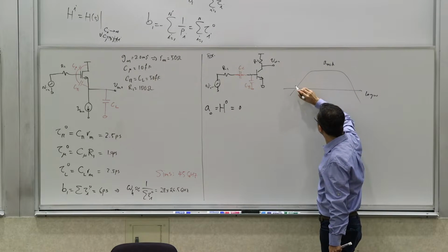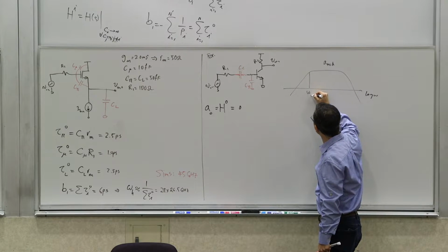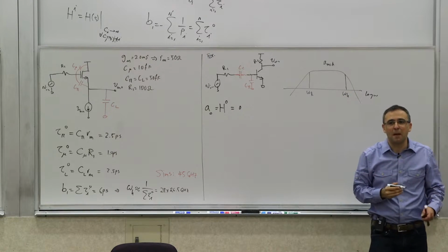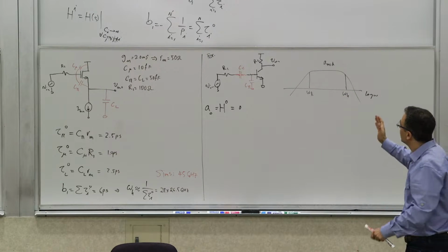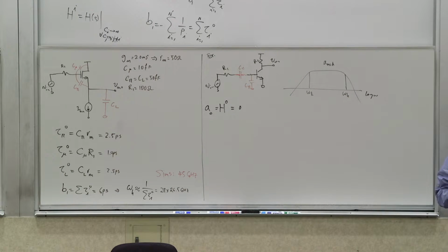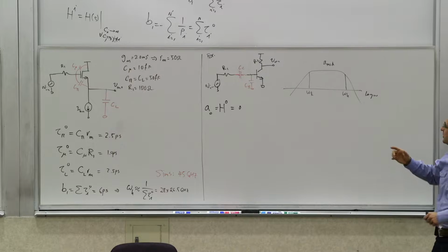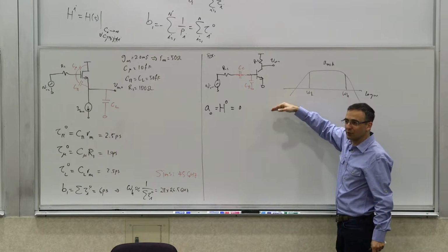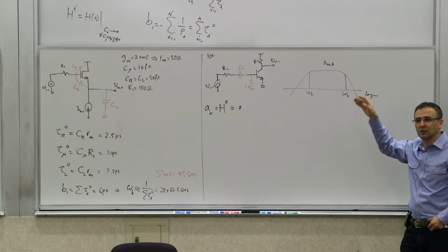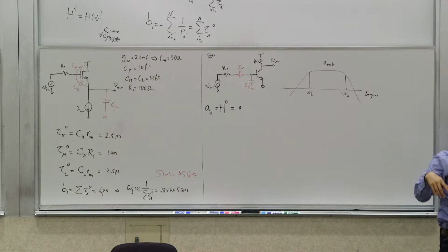Now, this high pass part of this, so this is what we call omega L, and this is what we call omega H. Right? This band, the low pass, the lower frequency part of it, the high pass part of this, is caused by what? Is induced by which capacitor primarily? Which one's responsible for it? CC, right? No, this part. Because this is the one that open circuits, right? And then this part is responsible, caused by C pi, or if you have C mu's and other things, they would kind of produce that. I mean, we just ignore those to make this simple.